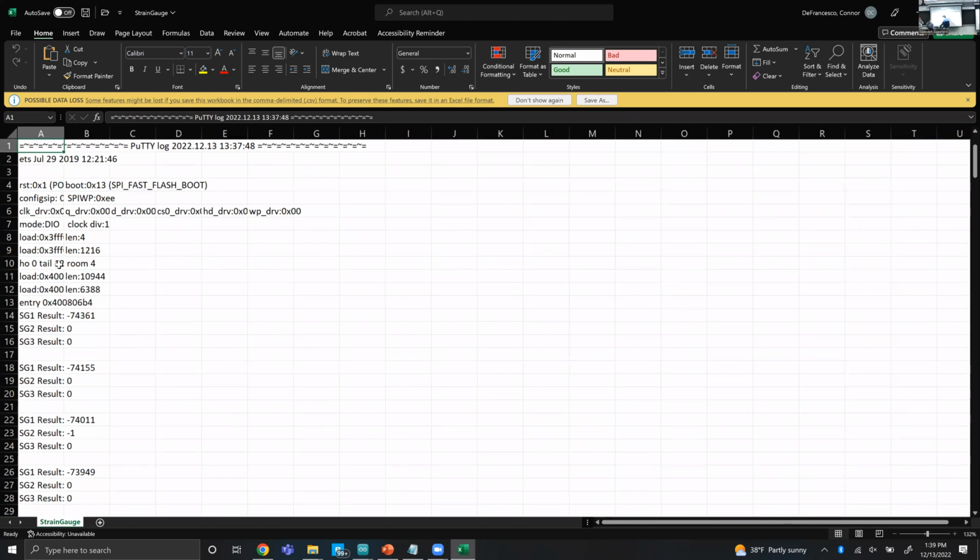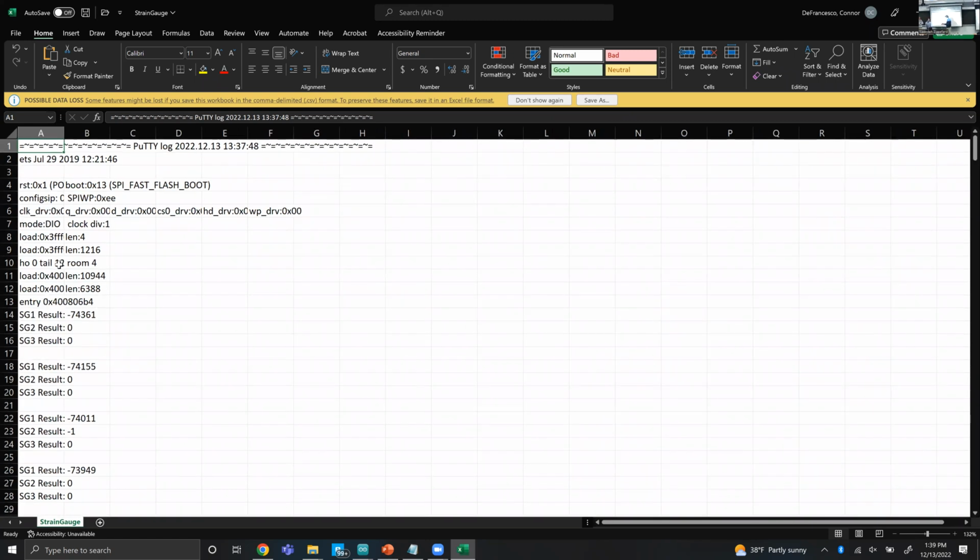So originally we were trying to show all three strain gauges, because all three work the same way, and we want to be able to show that, but because we don't have a power supply, it was just easier to show the one strain gauge. You have it on all three axes for the test stand? Correct. So one is for thrust and two are for torque. They will be on different devices, but they will all be measured at the same time.